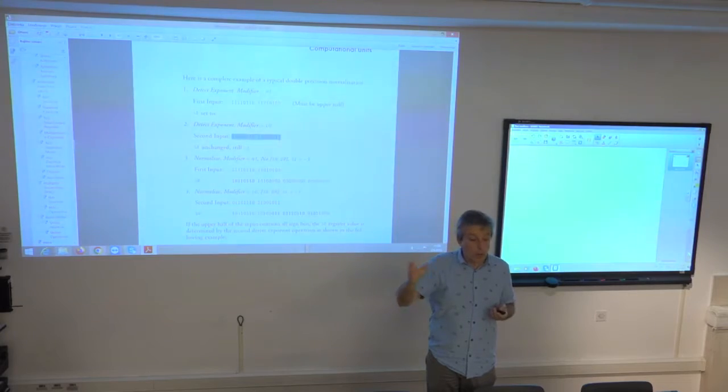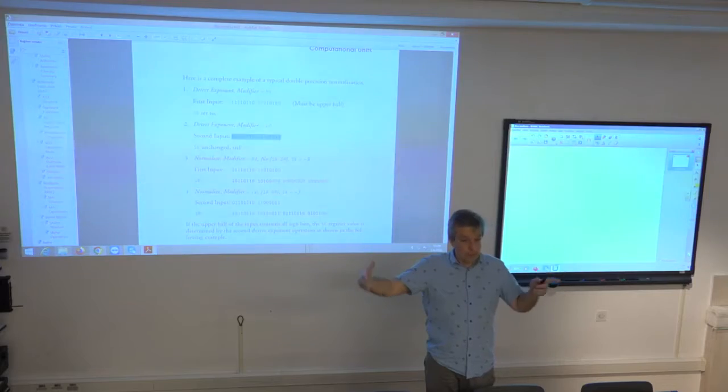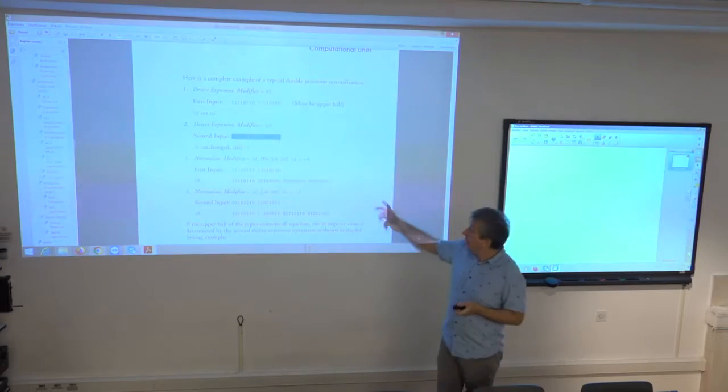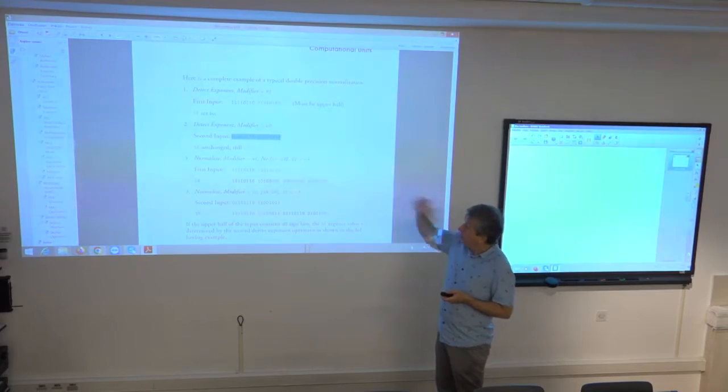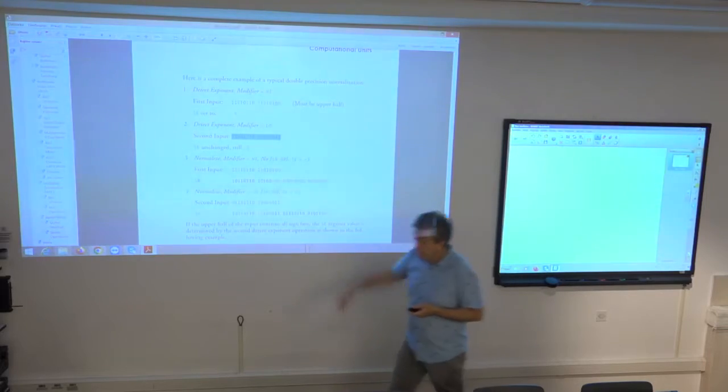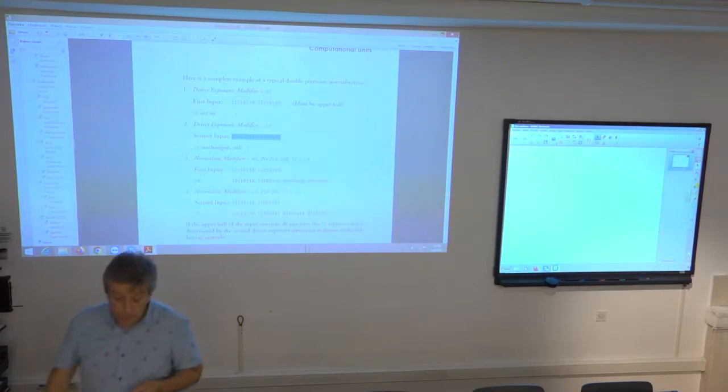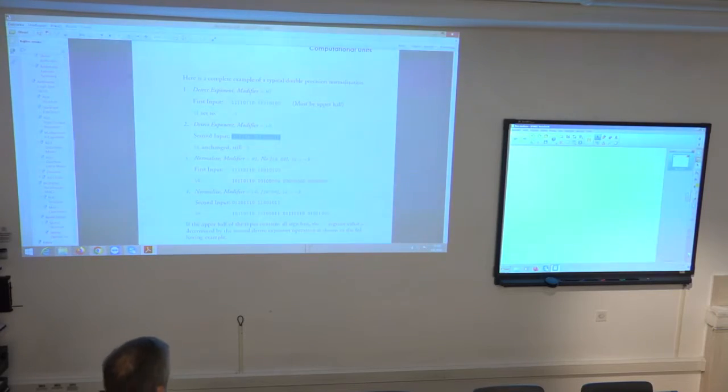So because the leading one is in the lower word, not in the upper word, but on the 17th position of this 32-bit value. So by combining these 2 exponent instructions for the upper word and lower word, you get the final exponent of the input 32-bit value with only 2 assembly instructions. And then once you have this exponent, you first normalize, for example, the upper word, and then use this OR operator to combine the result of the shifting of the upper word with shifting of the lower word.